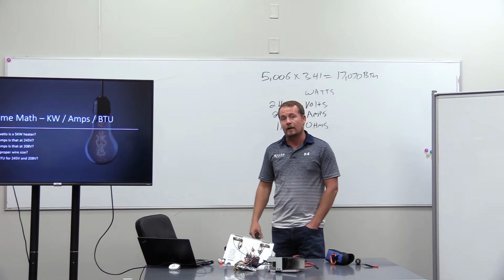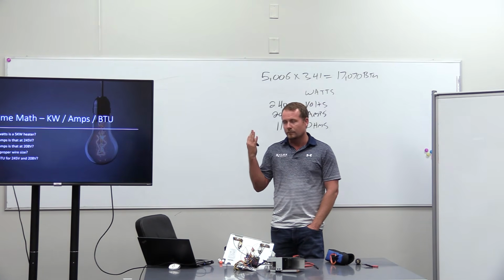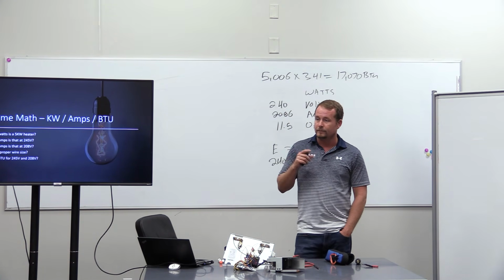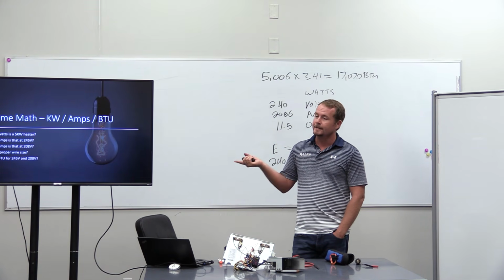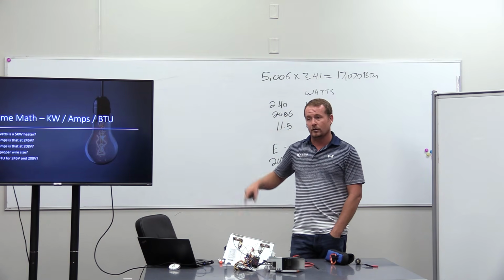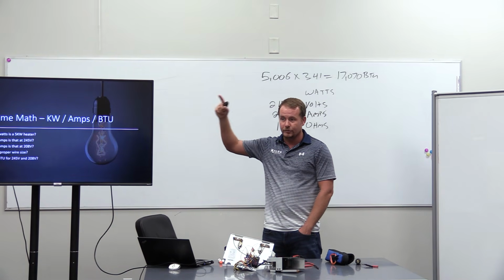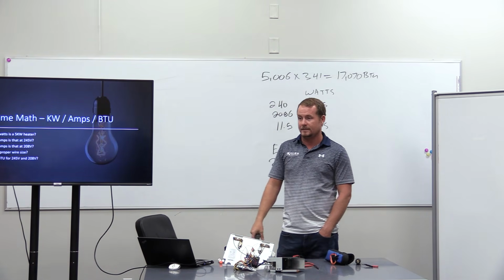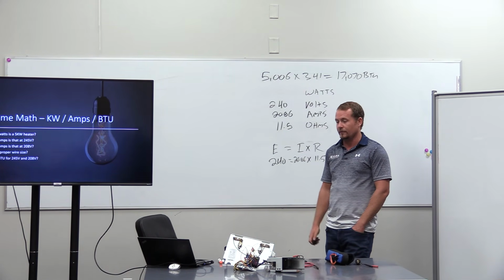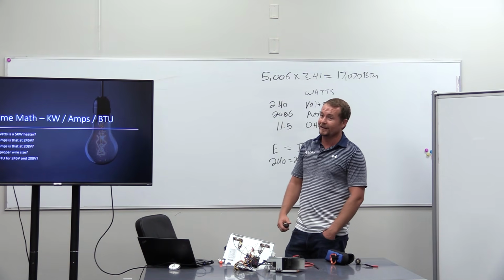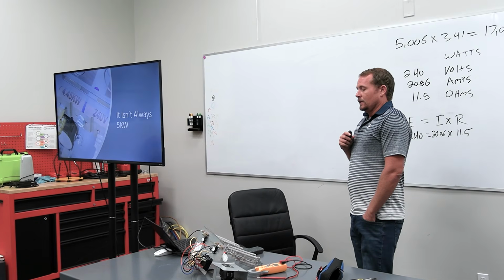Now, if you have 10 kilowatt heat, that's where it gets tricky, because what do most people run to a 10 kilowatt heater? Number 6 is typical, but is number 6 60 amps? Number 6 in the 60 degree column is actually 55. So you have to use slightly better wire in order to be able to use number 6. You can't use number 6 Romex to do that. Again, all these charts are readily available. This isn't a wire sizing class. We've already done that class, ad nauseum, right? All right, so we talked about this.